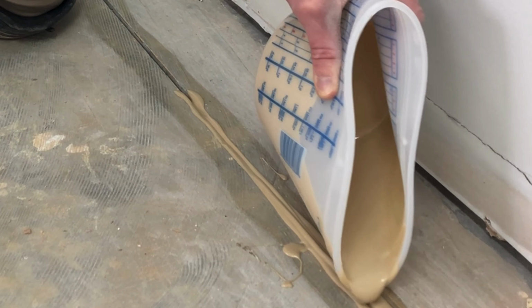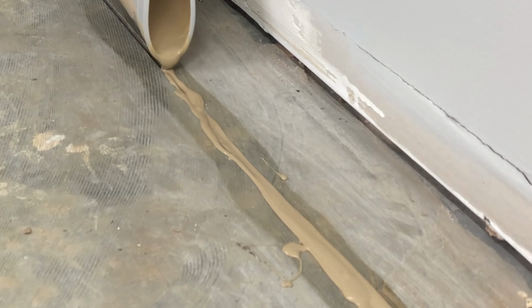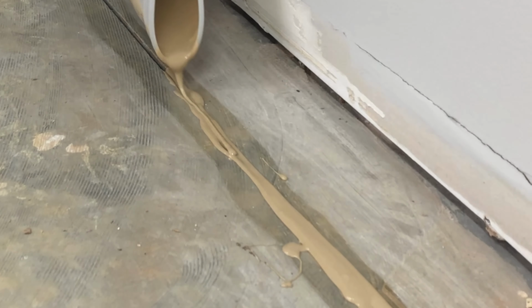For bigger repairs, you can get into a variety of different things. That could be a concrete repair mortar, that could be an epoxy mortar. There's different urethanes for those purposes. Something that's a little stronger than the concrete itself, but also thick enough to allow it to be placed either horizontally, vertically, or overhead. You have different consistency materials for those applications.